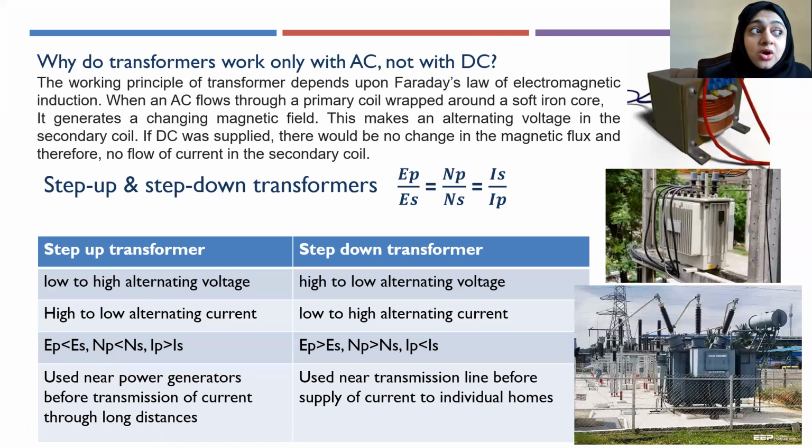So when we switch on, the current changes from 0 to say 3 ampere. And then its value will be 3 ampere itself throughout. There is no change. While in AC, if it's a 3 ampere AC current, the current will change from 0 ampere to 3 ampere, then it goes back to 0, then in the reverse direction 0 to minus 3 ampere, then it goes back to 0. It keeps on changing. It will change several times in a second.